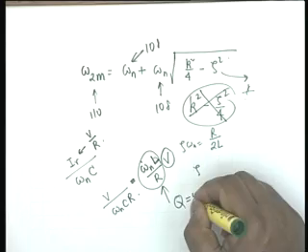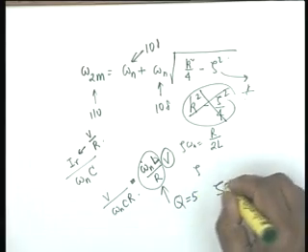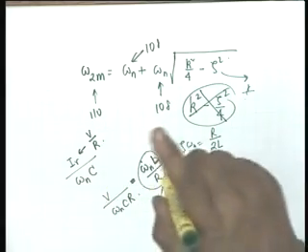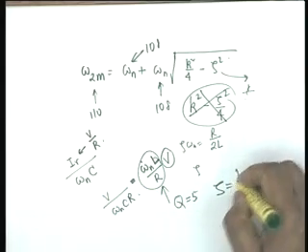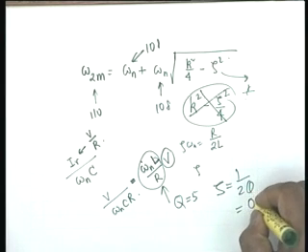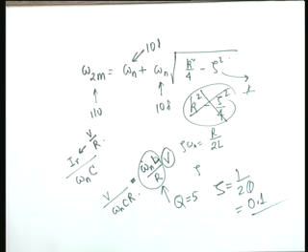Whenever you make a measurement, you measure the RMS value. Even if you take the peak value, it doesn't matter because you are taking ratios. So Q here is 5, and zeta, as you know, the definition of Q is equal to 1 by 2 zeta. So zeta is 1 by 2 Q. This is simply 0.1 because Q is given as 5. This was another alternative to finding the answer to the question. Yes, any other question?